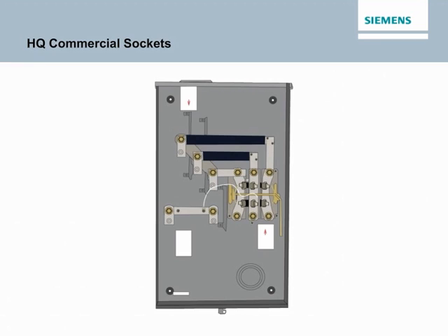Siemens lugs have either a 13/32 inch opening to fit 3/8 studs or 9/16 opening to fit 1/2 inch studs. It's important to make sure that the lugs ordered fit over the stud sizes in the meter socket. 200 amp sockets accept Type RX hubs, which fit 3/4 to 2.5 inch hub sizes. 320 amp sockets accept Type HD hubs, which fit 3 inch to 4 inch hubs. HD and RX hubs are all interchangeable with Milbank hubs.